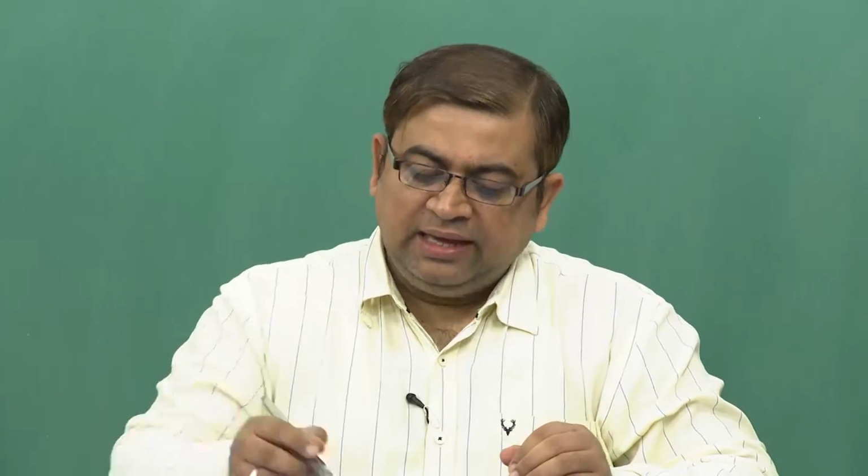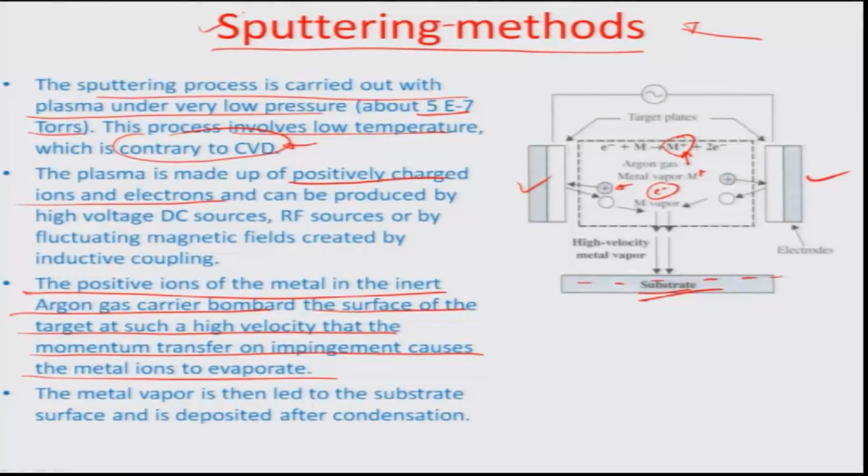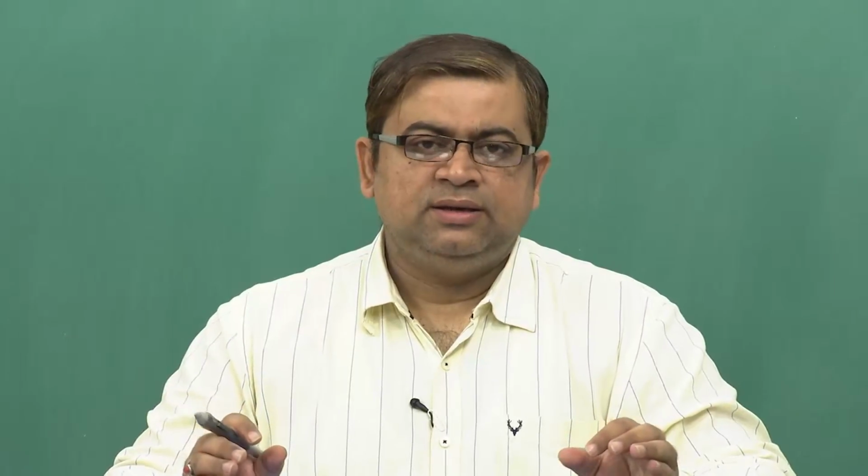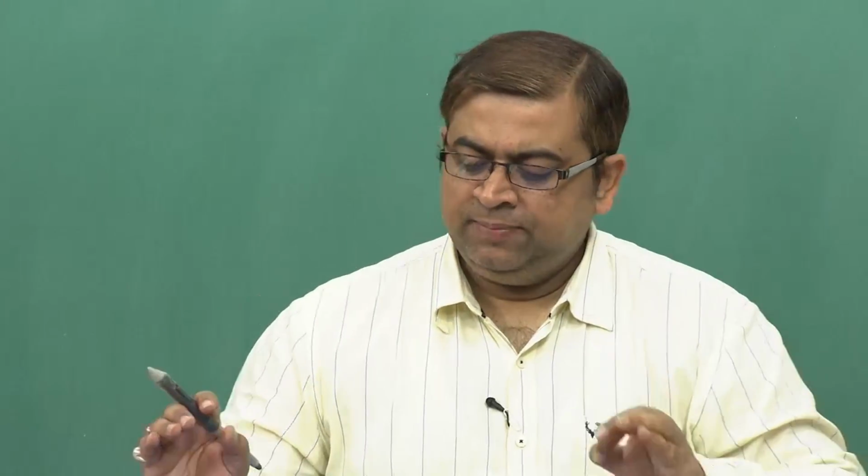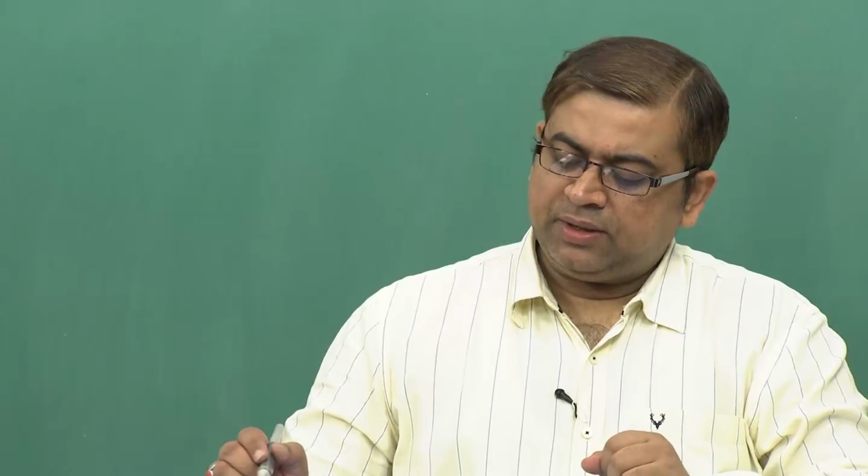It's a high throughput method, because in sputtering you can deposit thick layers, at least up to several hundred nanometers. And the other point is that you do not have to jeopardize the mechanical strength of the film, because there will be a solid film formed on the surface of the substrate.